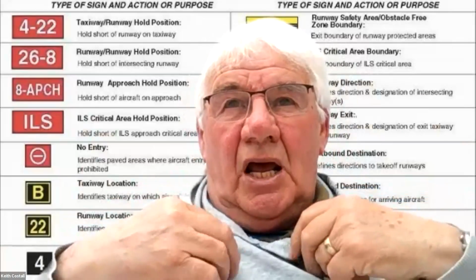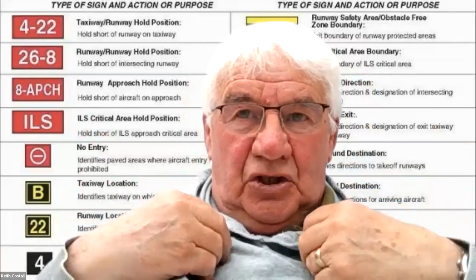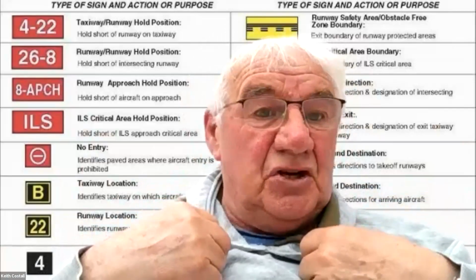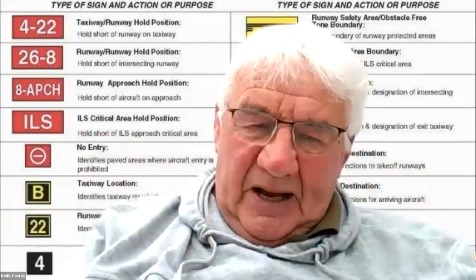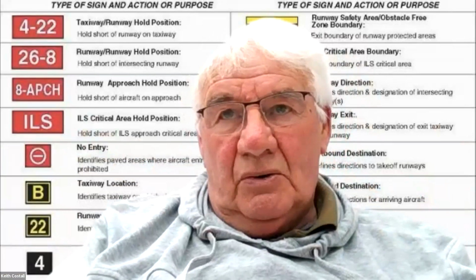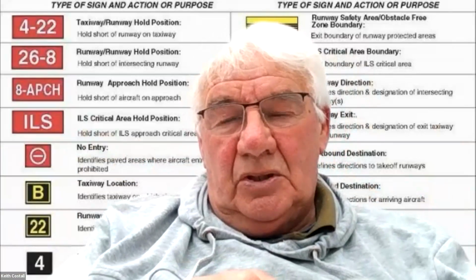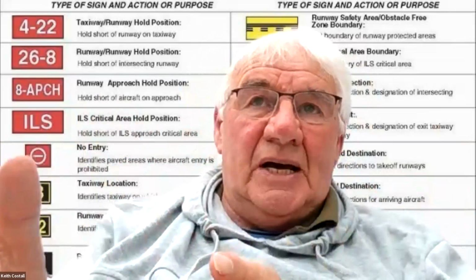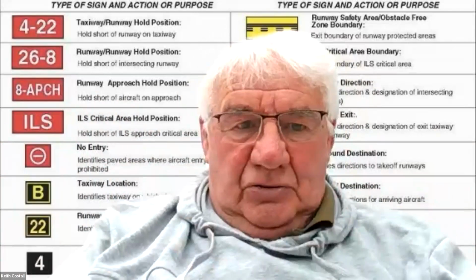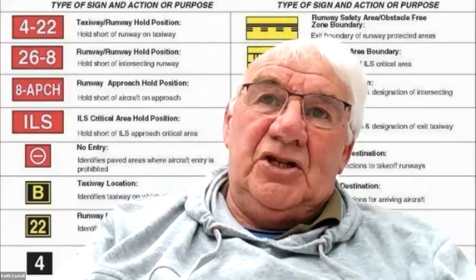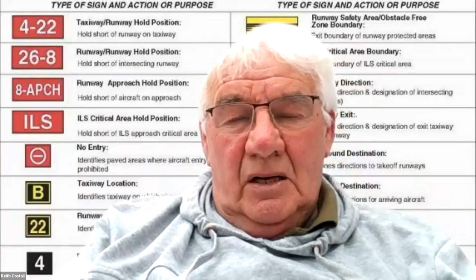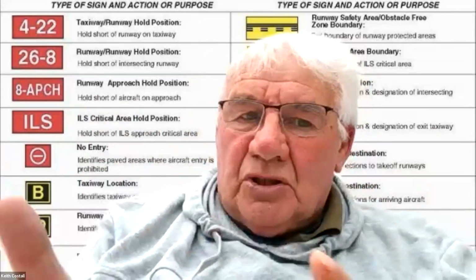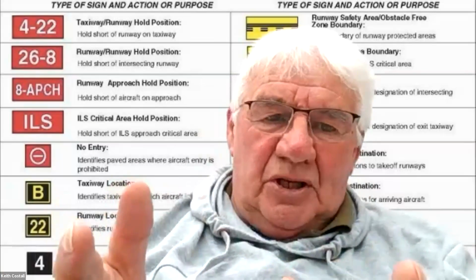Out of that, it was clear that not just cleaning was an aspect; it was the deterioration of the lenses created by jet blast, so it's been a good exercise for us to look at that. I certainly know that the manufacturers and suppliers of AGL lights will offer a with or without sapphire coating.